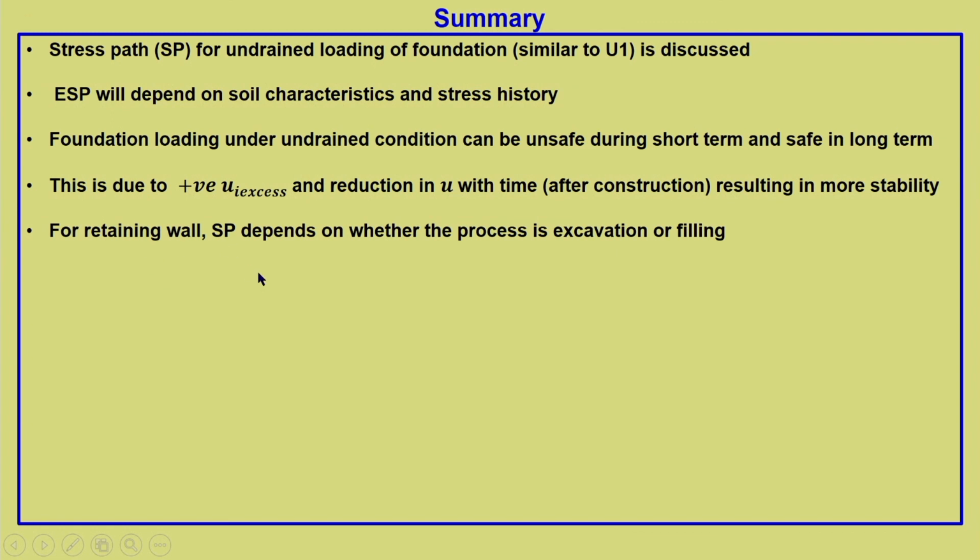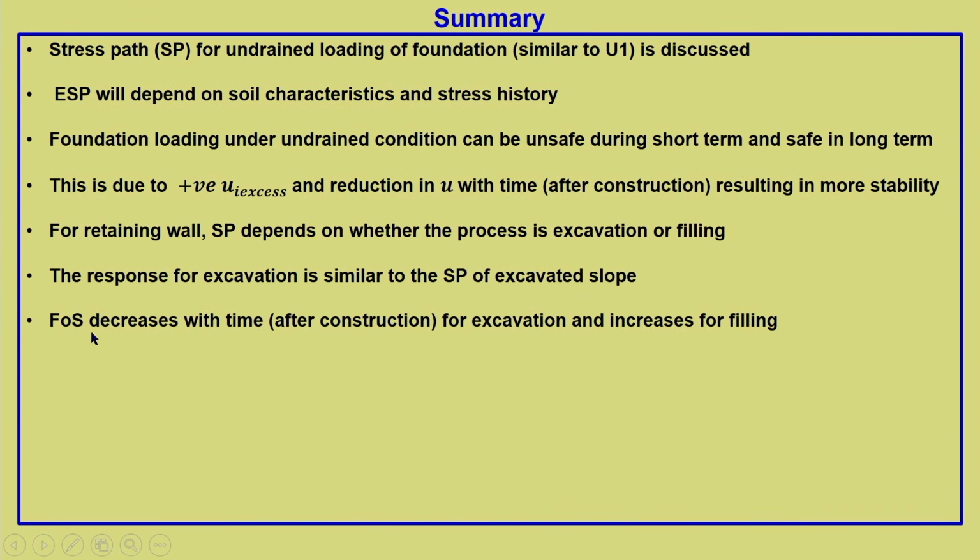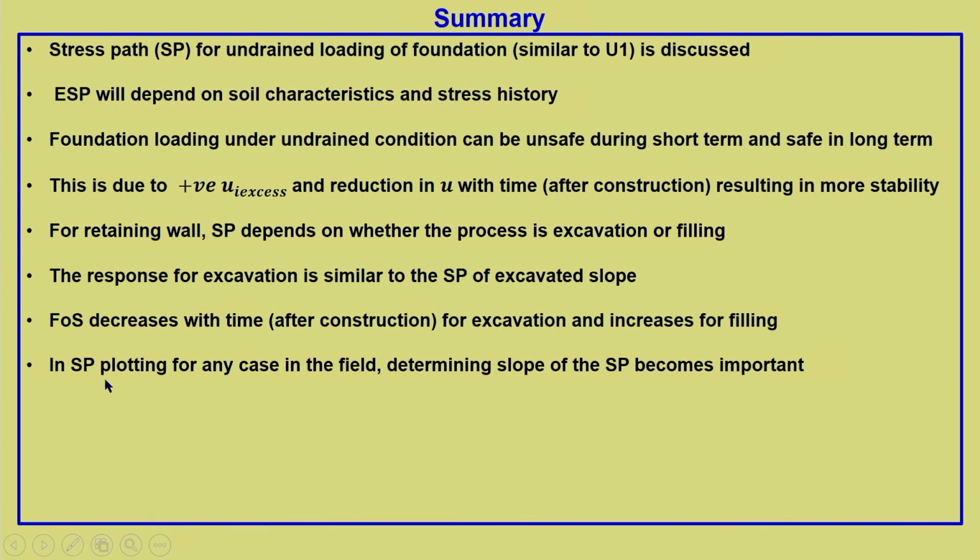For a retaining wall, the stress path depends on whether the process is excavation or filling. The response is totally different in both cases. The response for excavation is similar to the stress path of an excavated slope. Factor of safety decreases with time, that is, after construction for excavation, and it increases for filling. In stress path plotting for any case in the field, determining the slope of the stress path becomes important.